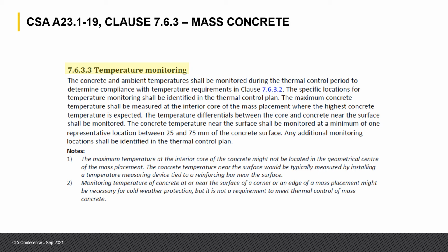Something important to address in the notes is that sometimes we see people specifying temperature sensors for thermal control of mass concrete in the corners, and we clarify here that if that is a requirement, it's only applicable to cold weather protection and is not a requirement for thermal control of mass concrete.